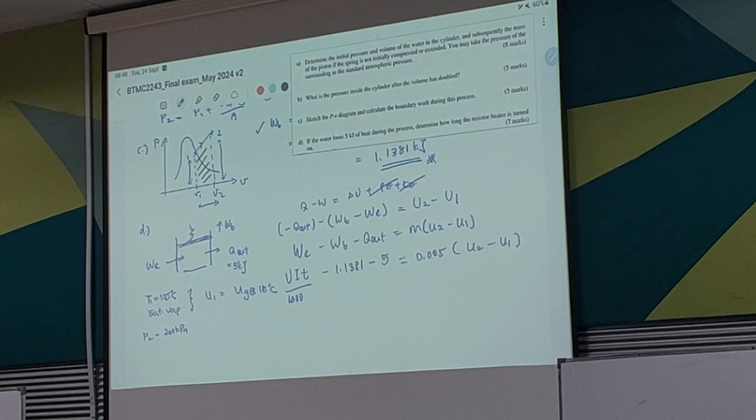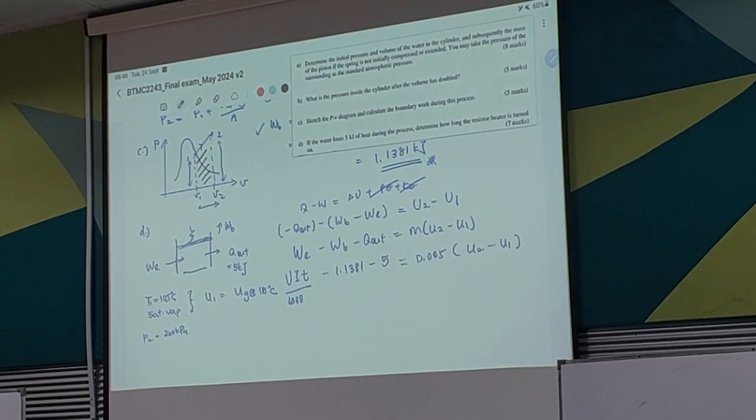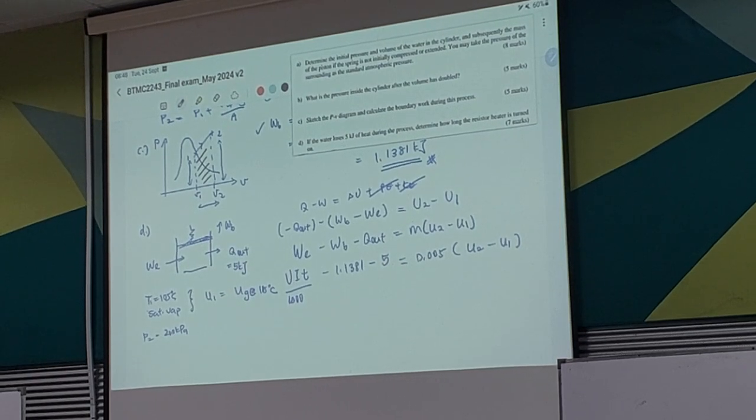If it is just superheated vapor, you don't have enough information, right? Because the superheated table doesn't really help you. Saturated, then yes, because for saturated vapor and liquid you can get the values from the table. But if it's a mixture, it also doesn't help you. Just like superheated vapor, you know it's from that table, but that is not one piece of information that you can use.